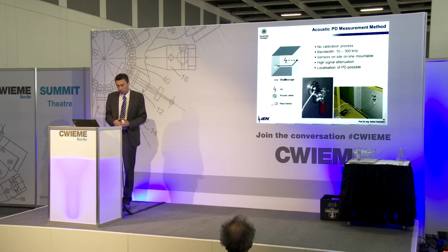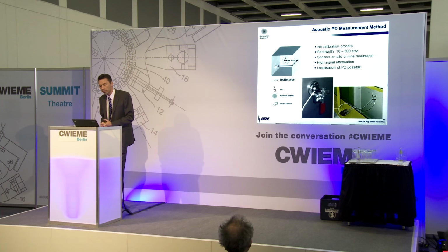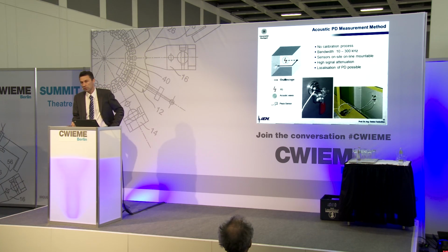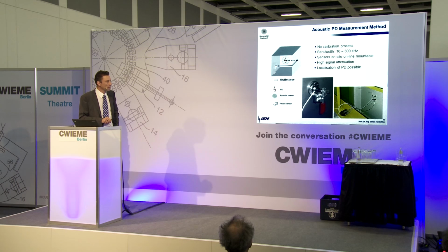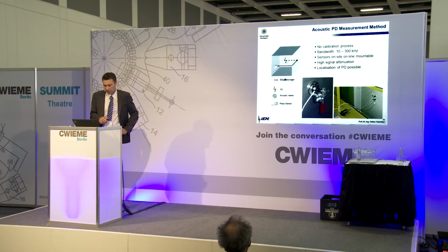And in order to measure free of noises, two other technologies were developed. One is the acoustic PD measurement. With the acoustic PD measurement you connect microphones to the transformer tank wall, and you measure more or less the acoustic emissions from the PD by these sensors. And therefore you have no problems with the noises which you have on the transmission line, because you simply do not detect them. You detect with this only internal partial discharges.